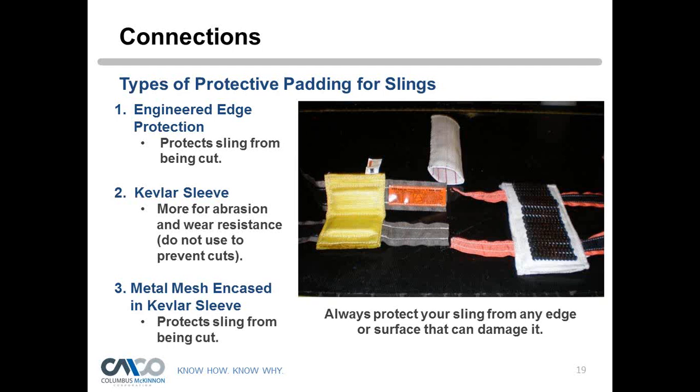And so that's why it can't come in contact with any load, because it's a much harder chain, you risk breaking it, bending it, and jamming up the hoist, or even losing it altogether. So that's why it always has to remain in a straight line and never should come in contact with anything. Okay. Hopefully that answered your question for you.